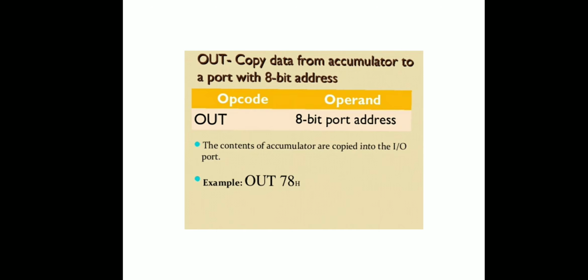OUT, copy data from the accumulator to a port with an 8-bit address. Here, the content of the accumulator is copied to the input-output port, which is specified by the 8-bit port address.